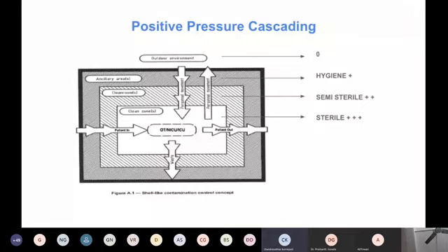We have to definitely maintain slight positive pressure with some hygiene filtration, where we dilute the infections and the particles from this level of the area. Along with the air, the zoning, the pressure, and the layout also play a major role in the initial cost of the machines and the recurring cost of the machines.